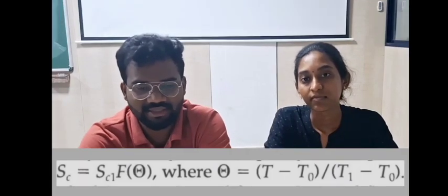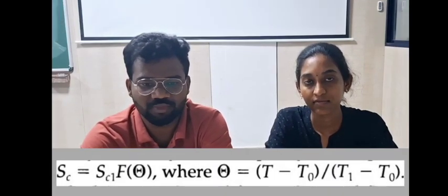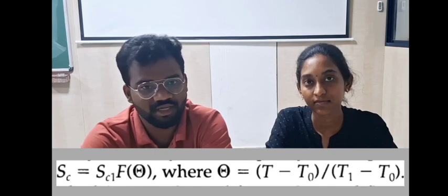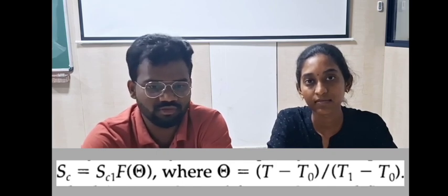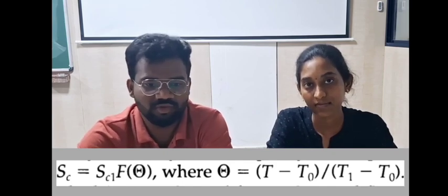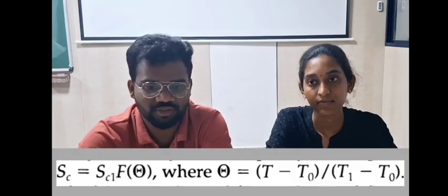Chandu, why do we use SC here? Here SC is the volumetric rate of thermal energy production by chemical reaction. SC in general is a complicated function of pressure, temperature, composition and catalyst activity. So for simplicity, here we represent SC as a function of temperature only.